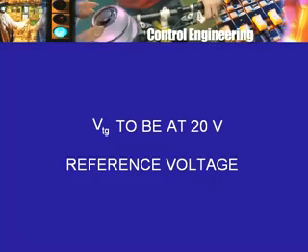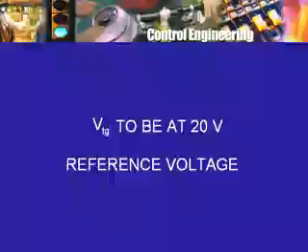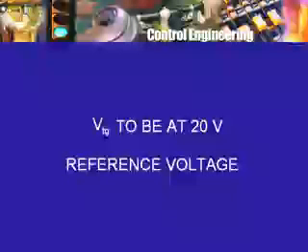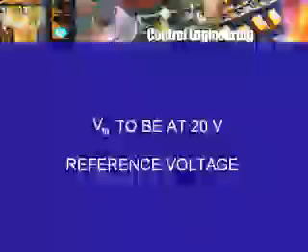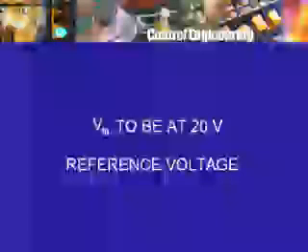If the speed is not 1500, but has changed to some other value, then the tachogenerator voltage will be of some other value, and we will talk about a different or a new reference voltage. So, this is a term that is very often used. In this case it is voltage. In general, one talks about this as the reference input.